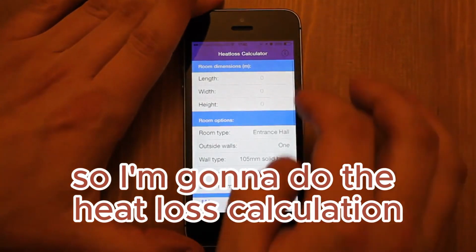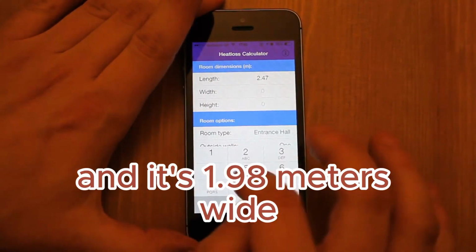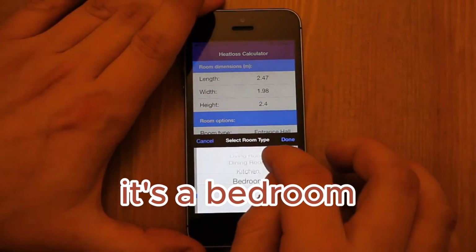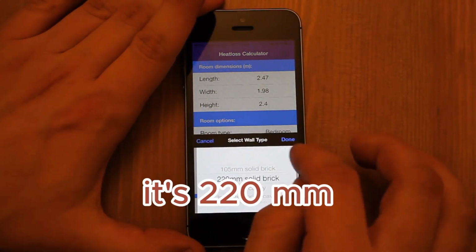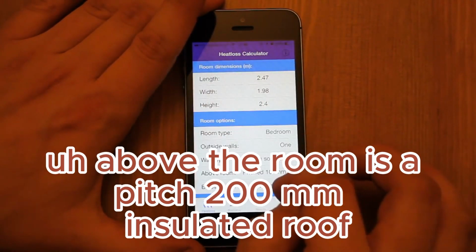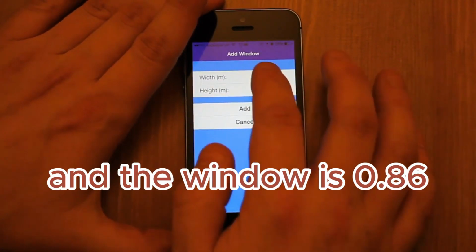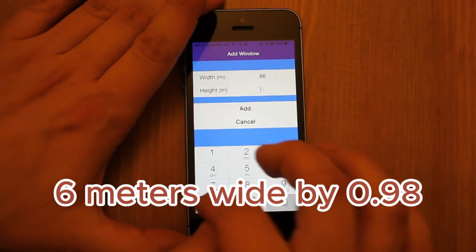So I'm going to do the heat loss calculation for bedroom 3. It's 2.47 meters long and 1.98 meters wide and a standard 2.4 meters high. It's a bedroom. It's got one outside wall, so I'll leave that outside wall. It's 220mm solid brick. Above the room is a pitched 100mm insulated roof, and below the room is a heated room. It's got one window which is plastic double glazing, and the window is 0.86 meters wide by 0.98 meters high.